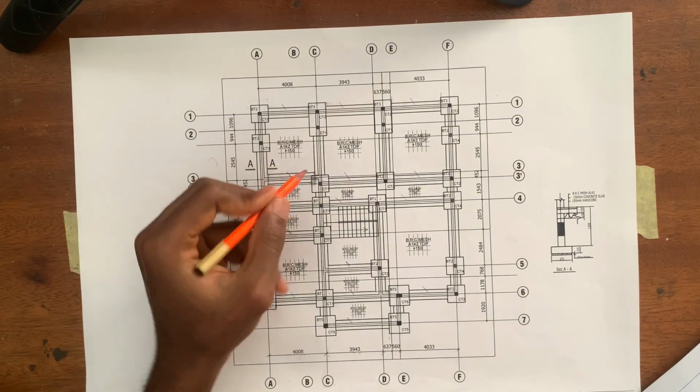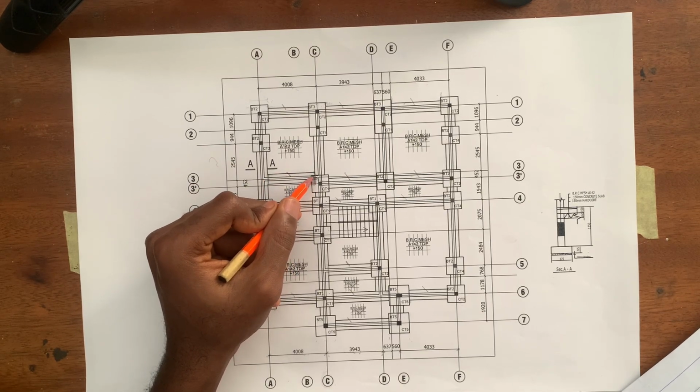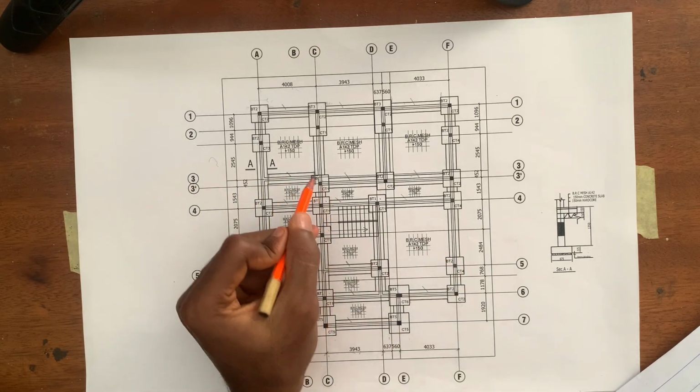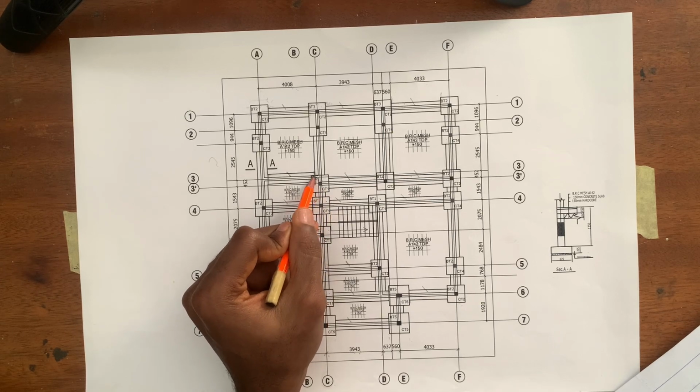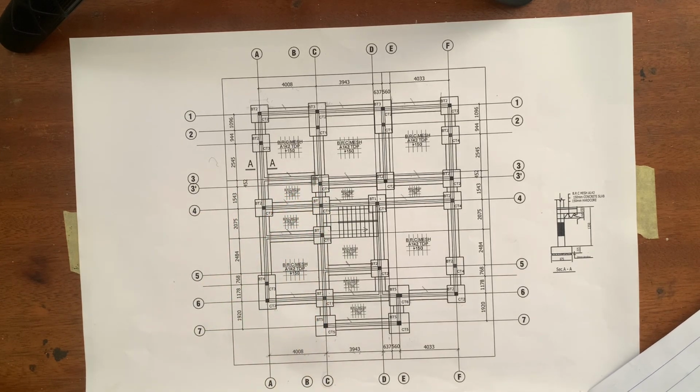So this extra that we have here has already been catered for when we were excavating for our column base. When we get our total volume for the trench, we are not going to be deducting that extra, because it has already been catered for in another item. If you don't remove it, we have over measured. I hope you understand.